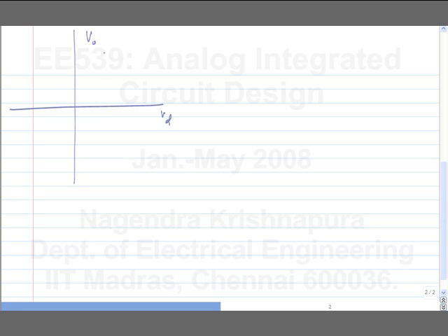let's say these are the differential output and differential input of the op amp. The characteristics are like this. You expect it to be something like this. Now the feedback network should have a characteristic with opposite slope. Okay, that's how you decide the signs. So we can go and turn all our op amps into fully differential structures. How do we go about doing it?